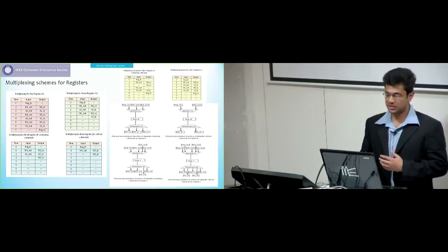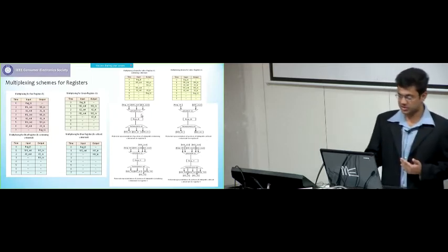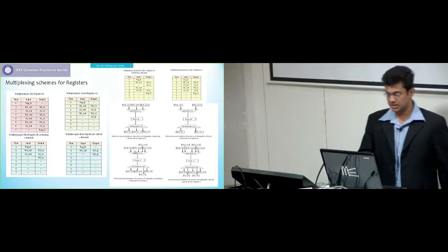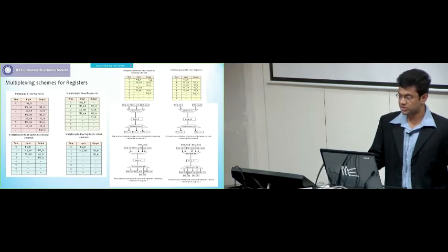Now once we have made the necessary changes to incorporate the watermarking constraints onto the multiplexing scheme table, we can extract the multiplexer circuit information from here. The multiplexer structure corresponding to the table given here is shown on the right, where you could see register I3, M4 out and A3 in are coming from here, and M3 in, A3 in and M3 in are coming from the last column. Similarly, the multiplexer circuit for register Y is based on these 4 input variables, and the output is derived from the last column.